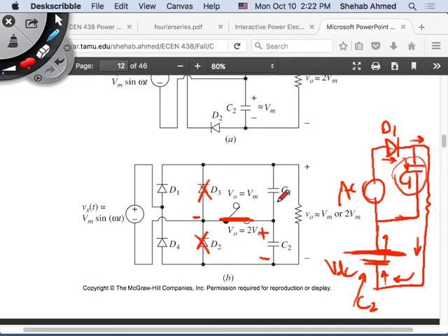As long as my time constants have been chosen properly, and I don't discharge any of them completely, I can create this voltage doubling action. If in the positive half cycle I charge C1, but I completely discharge C2, then I don't create the voltage doubling effect. Okay?